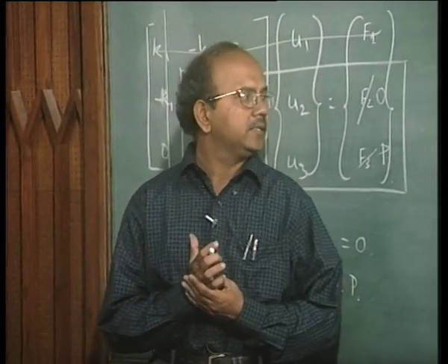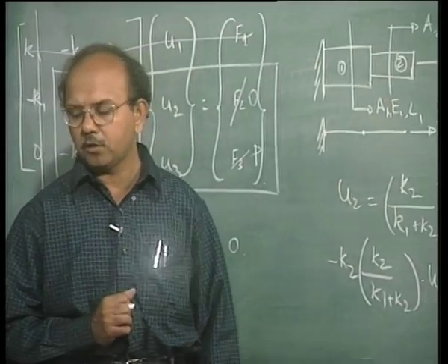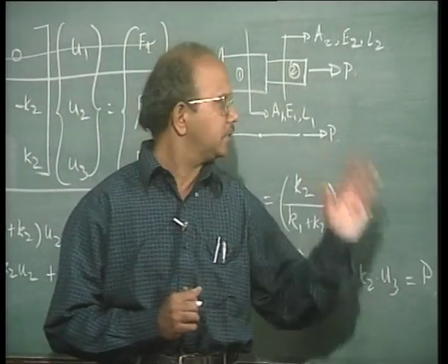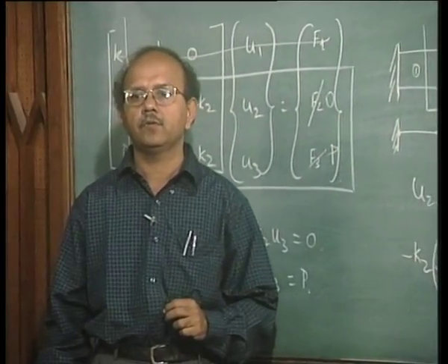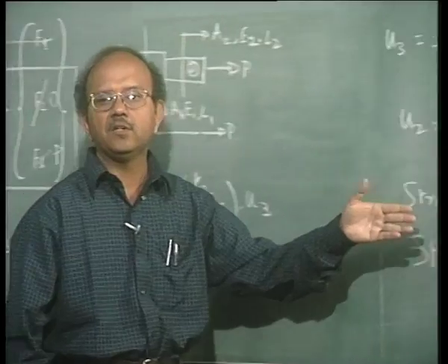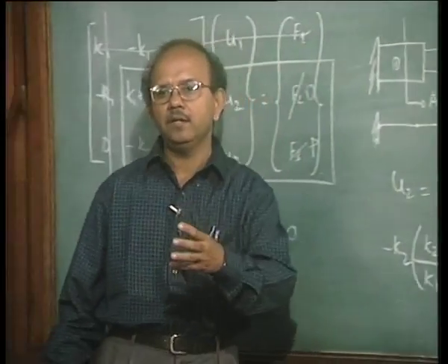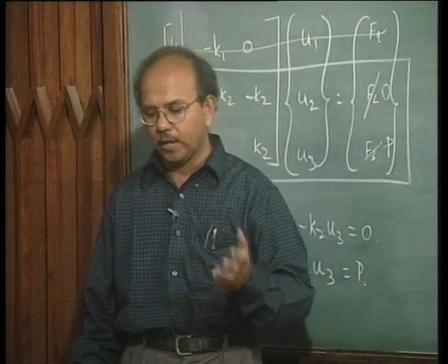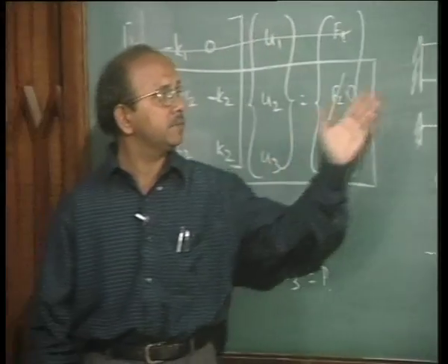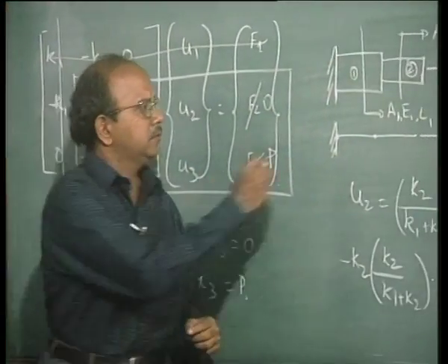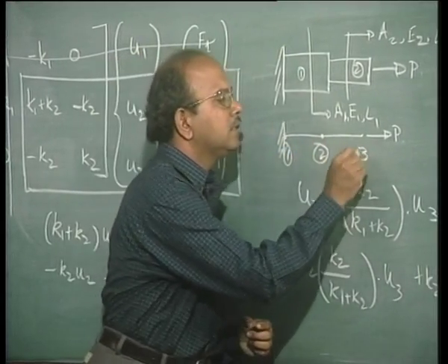So we first determine strain through the strain displacement relationship. What would be the strain? There are two strains, epsilon 1 and epsilon 2, that exist in the two bars. In this particular case, we can use the simple formula of change in length by original length. What is epsilon 1 in this case? Remember that we had called these node 1, node 2 and node 3.